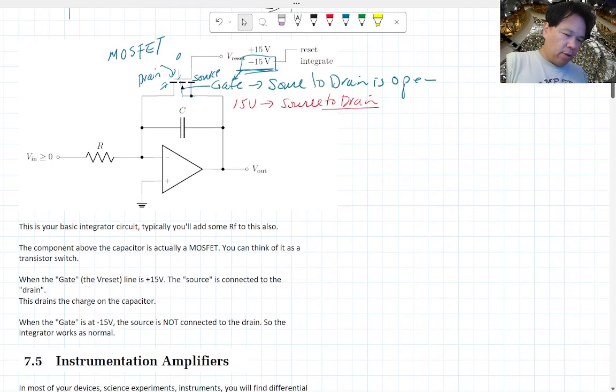So how that works is you have some pulse that comes in, and some resistors there generate some current. This is a very fast signal, so most of that will actually go through this capacitor. Therefore, you get an integration just as you expect.